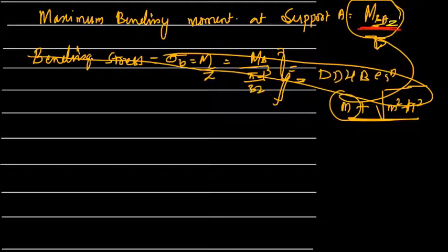As I said, you can get the diameter directly. In this case, as the shaft is subjected to two types of loads, you find out the diameter of the shaft using the maximum normal stress theory or the maximum shear stress theory. So now let us go for the diameter of the shaft.